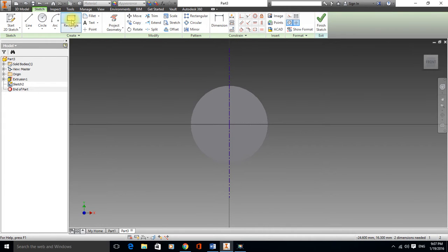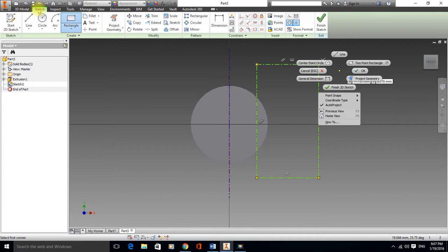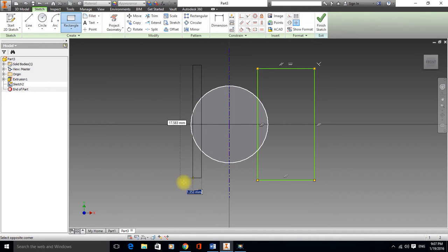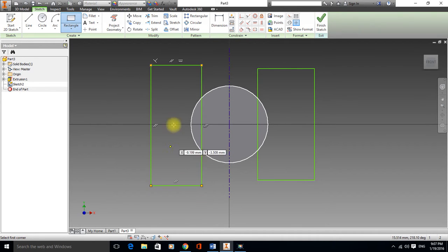Let's actually create our paths. We need to simulate our end mill. If we were holding it vertical and presenting an end mill down, we need to actually simulate what we're going to do. Rectangle. Every time you extrude, you need a complete profile. Rectangle automatically completes a complete profile. Let's just undo that, sorry. Unselect center line. Let's reselect rectangle. There's one. There's another. Okay, so they're both either side of our center line, and these are going to simulate our paths.